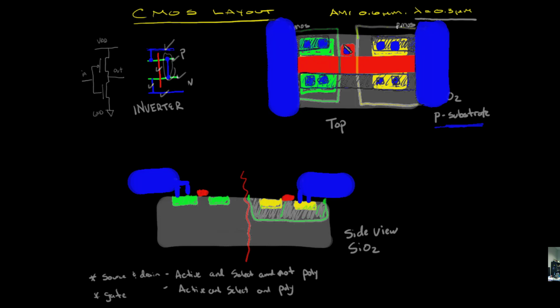And we're not really going to establish anything yet, but eventually we would connect that to the outside of the transistor, and so that the gate has its input. And by the same token, we would have another metal connection. We don't need another via because it's already connected, and that would become our out. Down here and connecting to a via here with a metal layer in between, and we're going to have a metal layer connecting our in and another connection to our out.